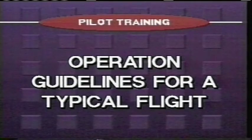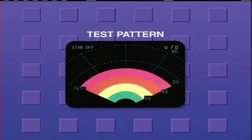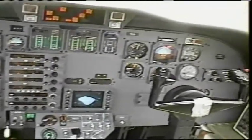A set of suggested guidelines for using a weather radar throughout a typical flight, as found in the pilot's handbook. While the aircraft is parked at the gate and taxiing in congested areas, keep the radar system in the test mode. Note, when the knob is switched directly from off to on mode, the display will blank.